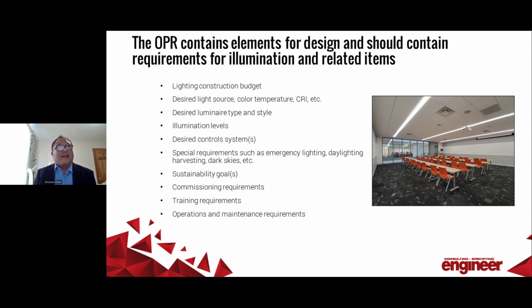So it's important to have this dialogue with the owner to make sure that you don't end up all the way at the end of a project and find out that you didn't meet the owner's requirements. And sometimes the owner's requirements don't line up with the energy code. For example, we had a project where the owner wanted all halogen lighting, and that definitely did not meet the energy code. So we explained this to the owner at the beginning of the project, and we were able to work in energy efficient lighting while still meeting the owner's project requirements, the OPR.